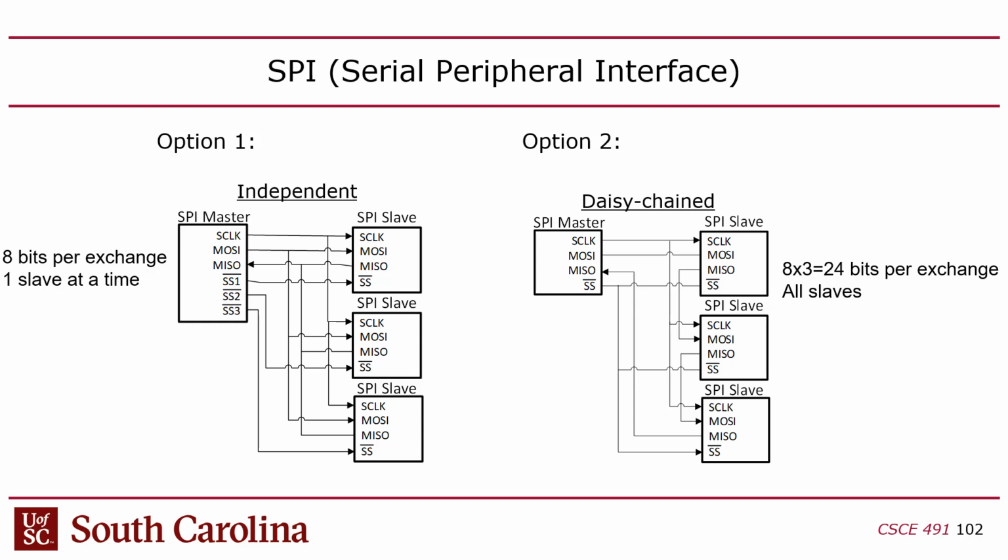You've got one guy trying to drive a wire down to 0 volts and one that's trying to drive it up to VDD volts, which is whatever the digital power supply voltage is. And what ends up happening is you end up with a short circuit, essentially. You short circuit the thing.